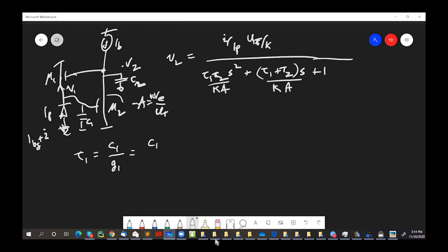You don't care about the conductance looking into the photodiode because it's a really small conductance, it acts like a constant current. So what was the conductance looking into the source of M1? Somebody can tell me that in subthreshold. Right, in subthreshold, conductance is the current divided by the thermal voltage. So this is the photocurrent over the thermal voltage. So that's the input time constant.